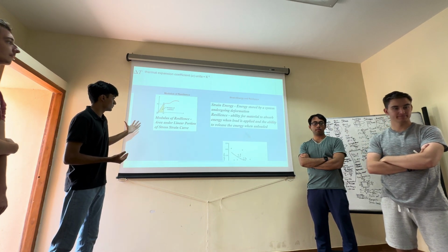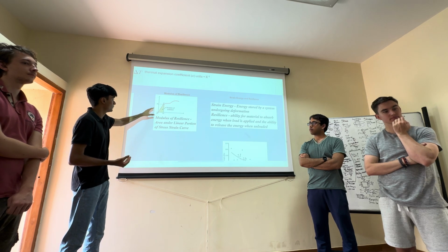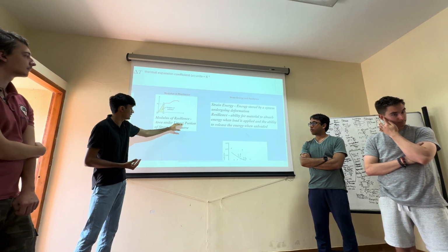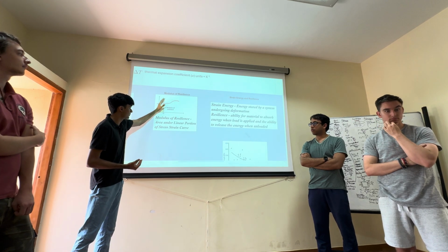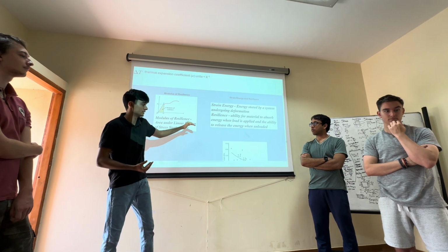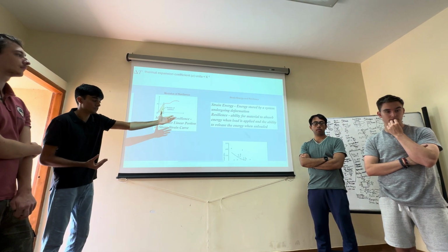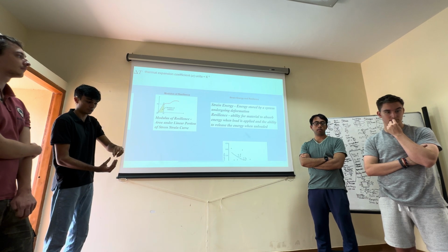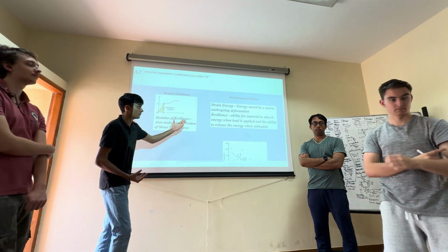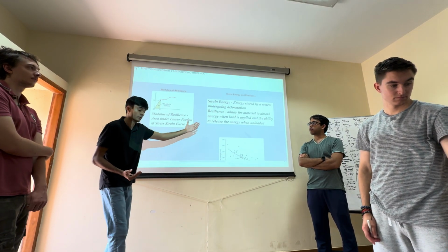So the modulus of resilience. We talked about the stress-strain curve a while back, and the modulus of resilience is the area underneath the linear portion, that initial linear portion of the stress-strain curve. Now, what does resilience mean? Resilience is the ability of a material to absorb energy when load is applied, or to release energy when it's unloaded. And the definition of strain energy is when energy is stored by a system undergoing deformation.